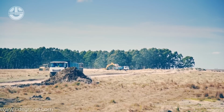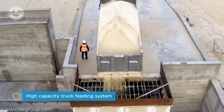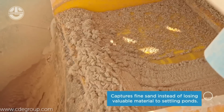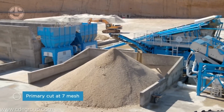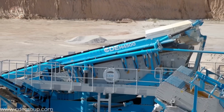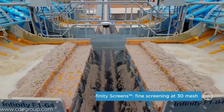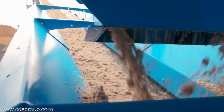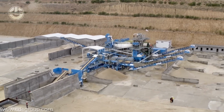The process begins at the feeding system, where dump trucks unload the crushed silica straight into the feeding system. This system regulates the feed to the wash plant. Next, the sand goes through a pre-screen which removes the oversized material with the primary cut at 7 mesh. The term mesh refers to the number of pores per inch. For instance, the 5 Infinity high-frequency Infinity screens cut sand at 30 mesh, meaning these screens have 30 openings on every inch of their screen.